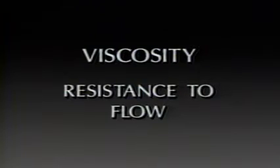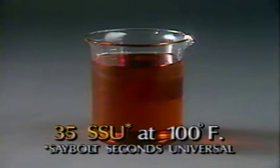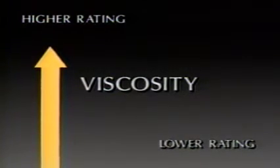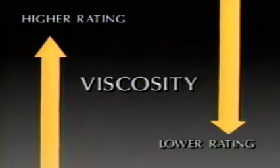It tells how long it takes a particular grade of oil to pass through a specific opening size at a specific temperature. The viscosity rating shown here means that it took 35 seconds for a specific amount of fuel to pass through a standard measuring orifice at 100 degrees Fahrenheit. The higher the viscosity rating, the slower the oil will flow through the fuel supply system to the burner. The lower the rating, the faster the oil will flow to the burner.